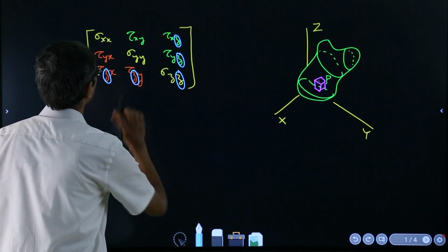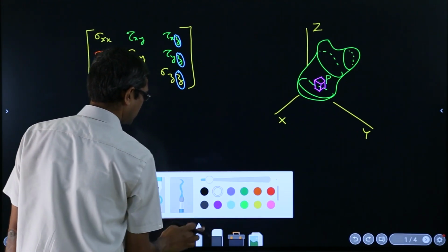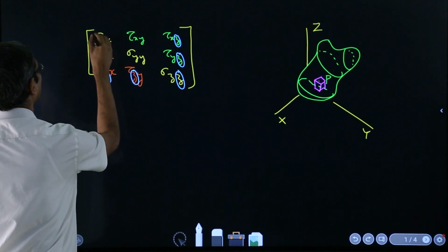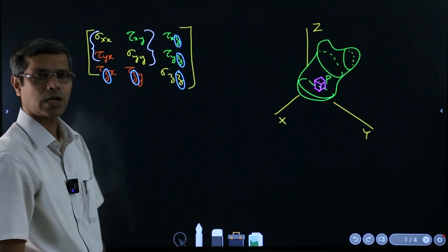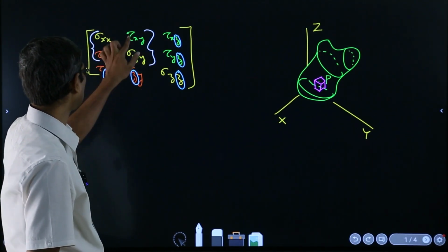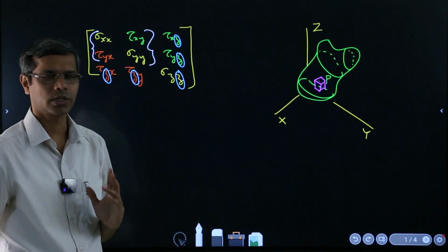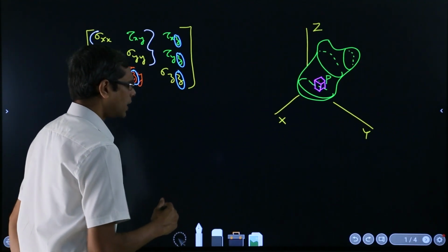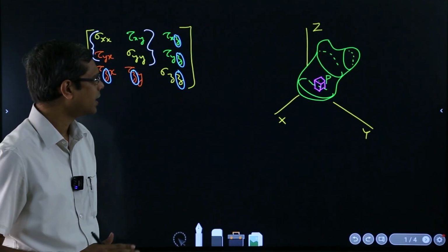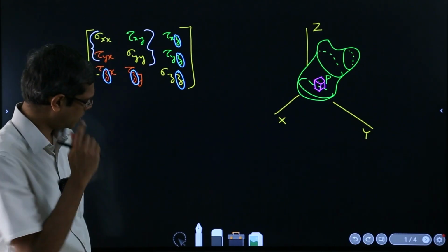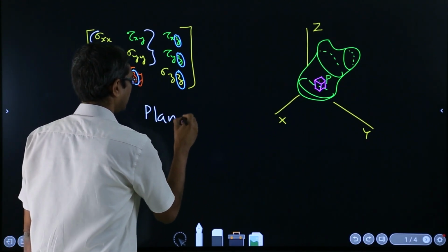Yeah. So all these things have actually gone. So we are left with this many, right? Tau xx, sigma xx, sigma yy, tau xy and tau yx, which are anyway symmetric. So there are 3 values which we are now concerned with, and that kind of condition or situation has a name. It's called the condition of plane stress.